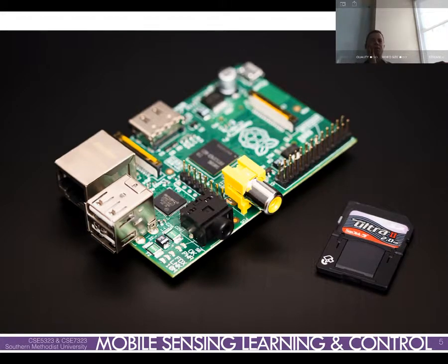Is this an embedded system? It is. It is, not can be. It's got all of these peripherals connected on it, right? It's got an HDMI out so that you can watch video from it. This is a mobile embedded system, right? It's running Linux, which is a little weird for an embedded system to be running an operating system, but it's also a minimalist Linux that it's running. It's not a real-time Linux or real-time OS, but that's okay. It's still an embedded system, even though it's got an OS. Typically, we don't have an OS on it.